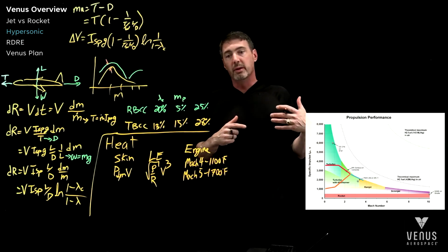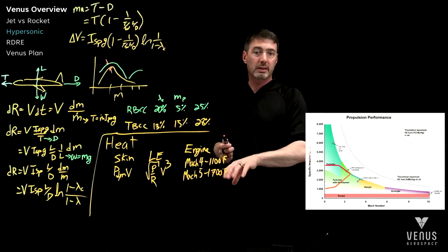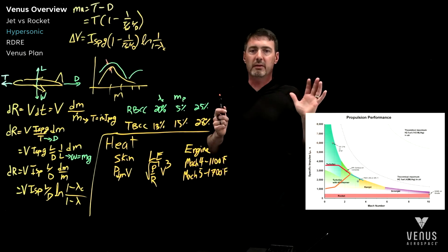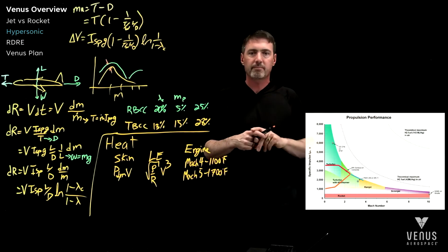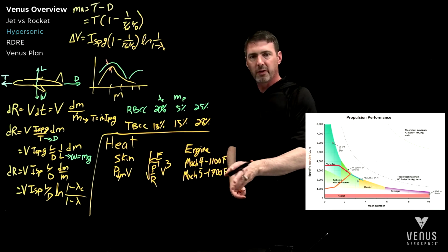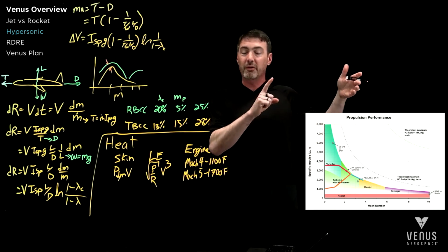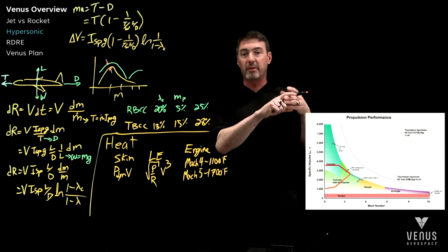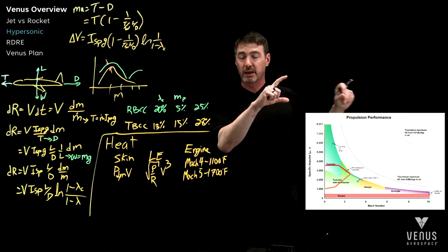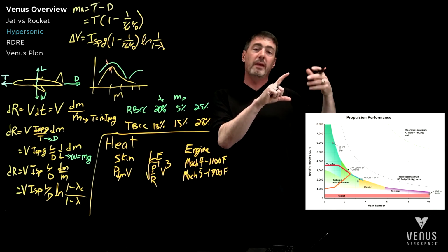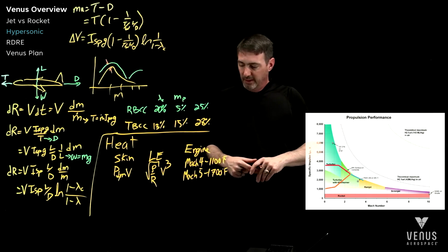And so if you remember, in the overview I talked about scramjets, that's part of what scramjets are trying to do: at these higher speeds, you really can't slow down the air, it gets too hot. And so what they're trying to do is, well, don't slow down the air as much. Let's try and combust supersonically. That's the idea behind the scramjet, and it's really trying to solve this problem. It ends up picking up some other problems because now the airflow is going so fast. You actually have their major problem inside of this combustion duct: my air is supersonic, and can I actually mix the fuel in with the air that's going that fast and combust it in time? So that's one step.